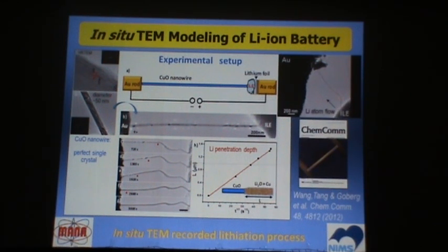The structure changes. You can see some type of crystal to amorphous transition. And what's good is that at every stage of this process, we can stop, we can analyze the chemistry, and we can get an idea what material is good, what material is bad for serving as the anode of lithium-ion batteries, because for this type of device, reversible cycles are important. If something is irreversible, like phase transformation or chemical transformation, the material is not good anymore.